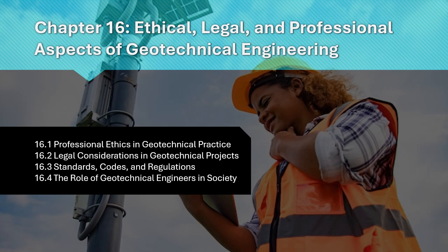BSI, British Standards Institution in the UK. BSI standards like BS 5930, Code of Practice for Site Investigations, and BS 8004, Code of Practice for Foundations, provide detailed guidance for geotechnical investigation and foundation design. Australian standards, AS in Australia.